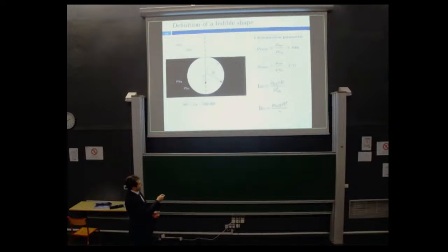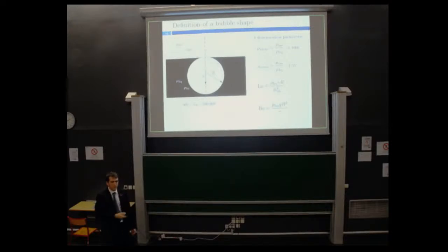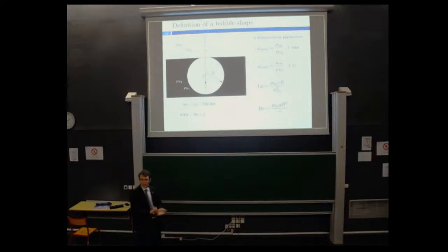Now, I'm talking about the Bond number here, the last dimensionless number. This number is comparing the gravitational forces on the top with the capillary forces on the bottom. And for the bubbles coming from breaking waves, the Bond number will be between 10 to the minus 3 to 1. So as you can see here, with the value of our two dimensionless numbers, the capillary forces are the main forces during this process. So we will be completely driven by the capillarity.